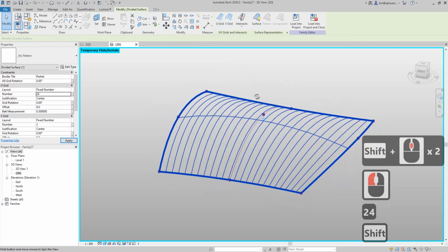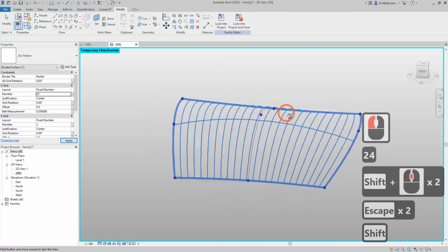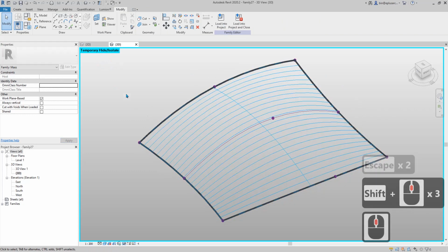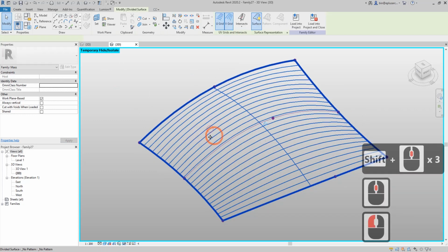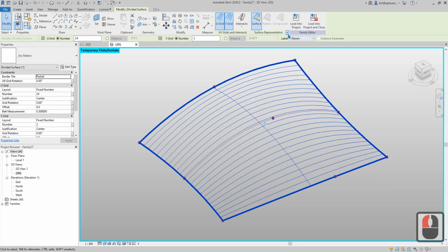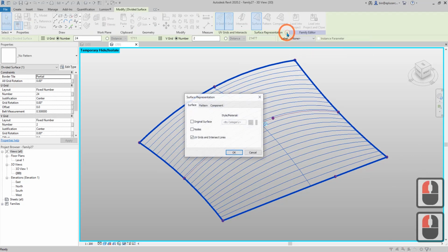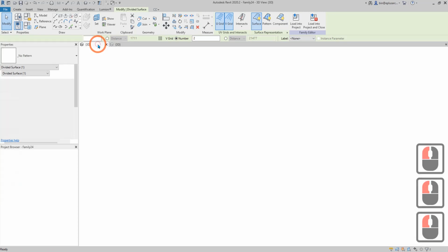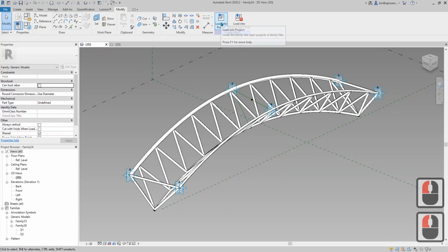No, yeah. Okay, so like this, and then load. Before I load, I'll click on this end surface and click on this little arrow and check the nodes. OK. Now go back to the truss family, load into project or helm.